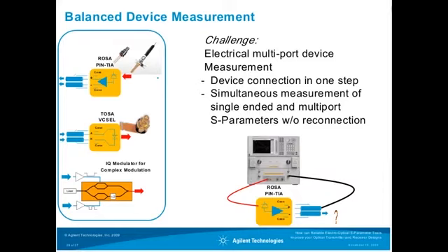We have here a few examples. One of the most common is a receive optical assembly, which consists of a PIN diode connected to a transimpedance amplifier which drives two electrical output ports, which are operated in push-pull. On the other hand, on the transmit side, we have a transmit optical assembly, which is basically a VCSEL device, a laser device.